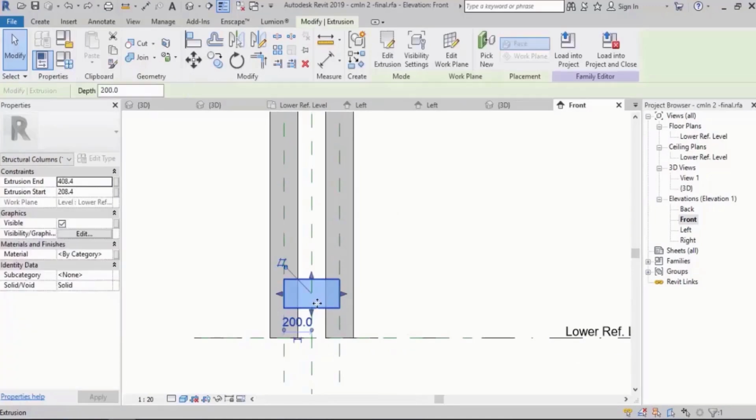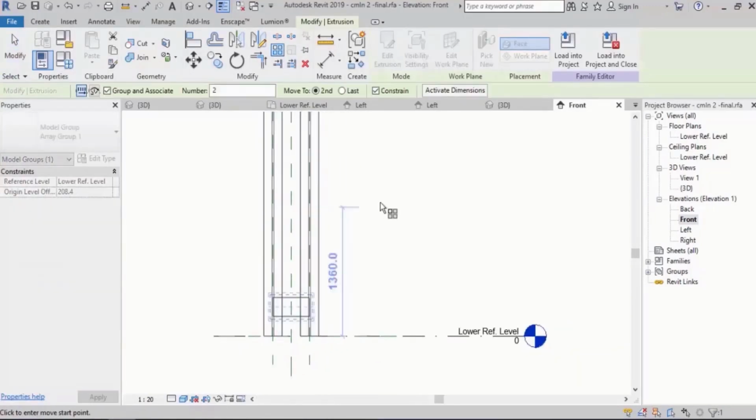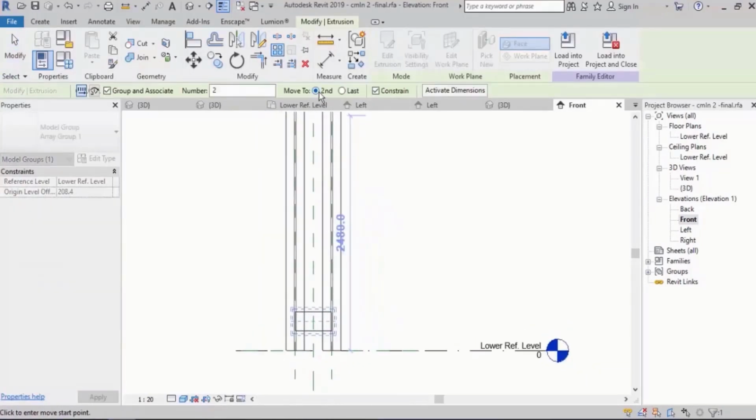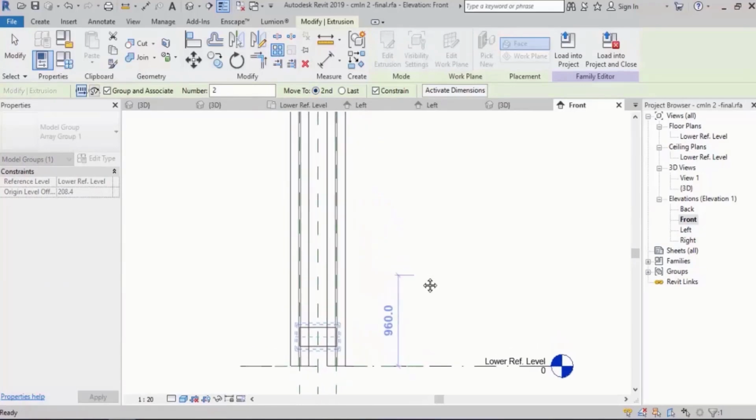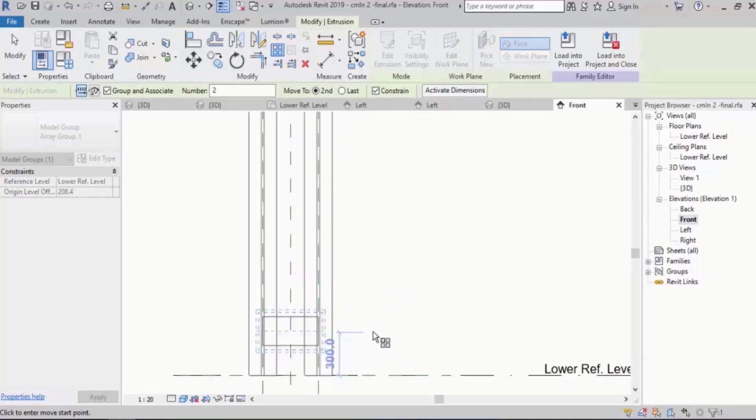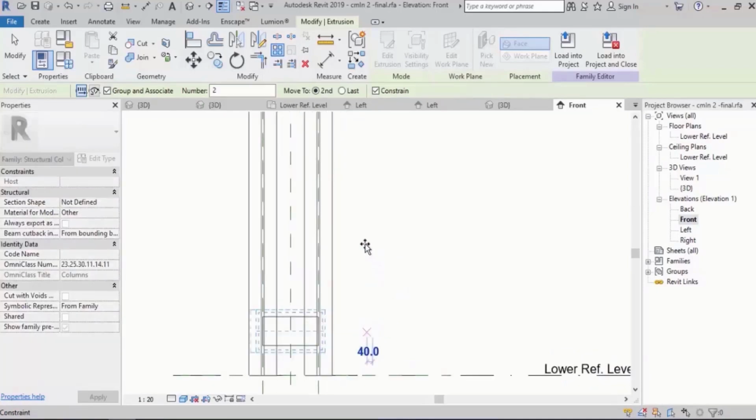So select it and select array. And obviously use second, right? Because we were about to give the distance of each sheet to the next sheet, which is 50. Now, it does not go up, and I learned that we need to inactivate a constraint.